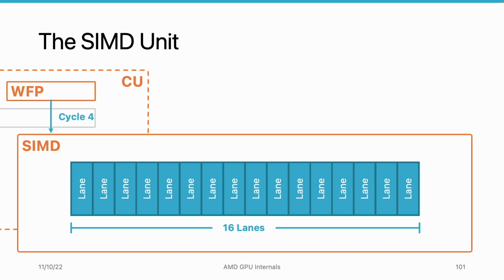So for some gaming GPUs, there may be no double precision computing capabilities. And for some high-end gaming GPUs, the ratio may be 1:8. That means there are 2 double precision lanes per SIMD unit. And for high-end compute-oriented and professional GPUs, it's typically a 1:1 or 1:2 ratio. That means there may be 16 lanes for double precision computing.